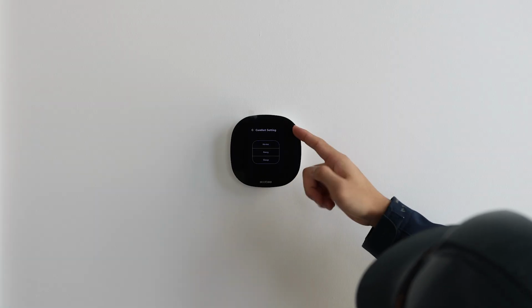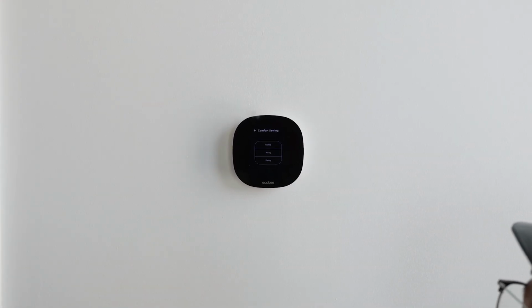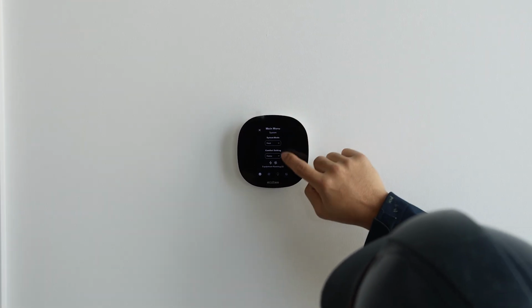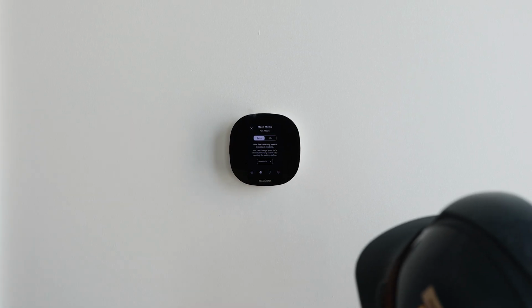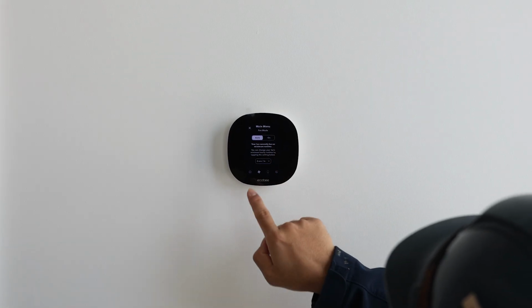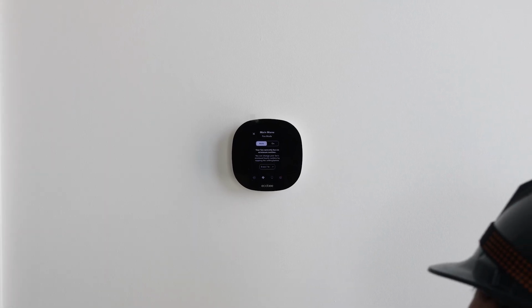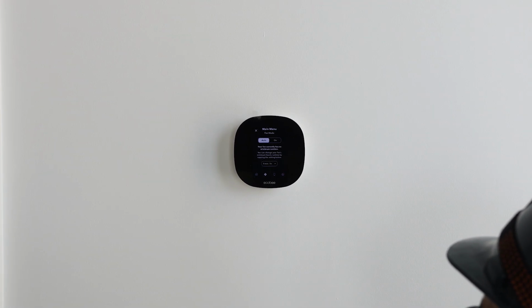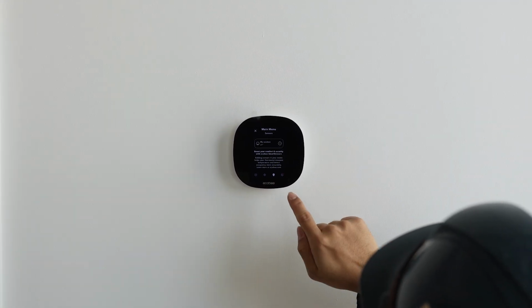And then here, a comfort setting, you can set it to we are home, or we are away, or we are sleeping. It's kind of like the schedule we did for the other room. Then go to next, fan mode. Fan mode will have auto mode or on mode. On mode means the fan will be running the whole time. Auto mode means the fan only turns on when there's a call for heating or call for cooling. Here it tells you the sensor rating.